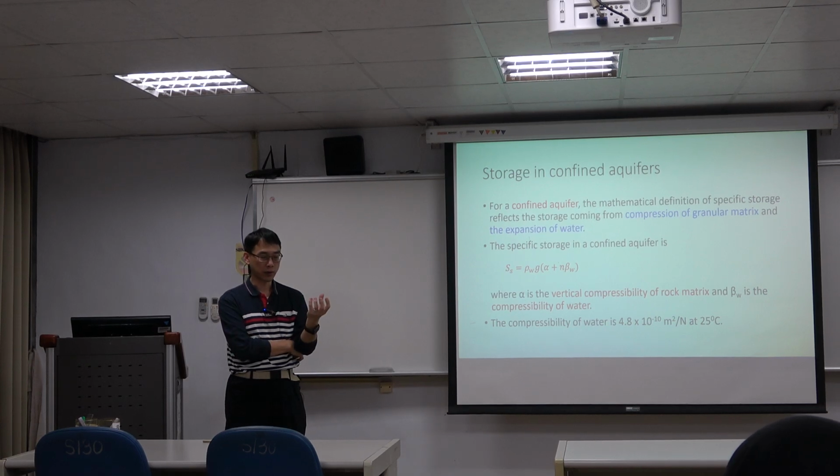When you take the core sample back to the lab, what you obtain is the small scale K value. Honestly speaking, it is not able to represent the real in situ K value. Because the scale is very different, they are not able to be used directly. Although we commonly still input the K value, if you do not do the in situ calibrations, that K value is not realistic for usage.